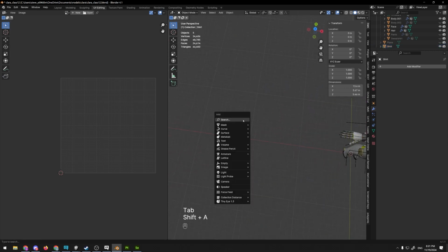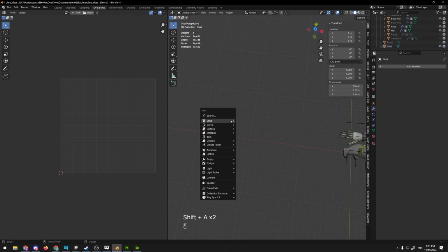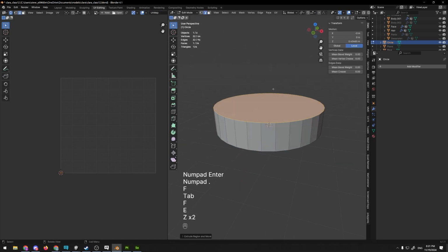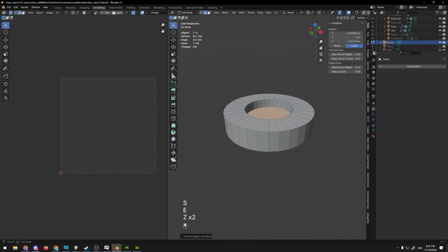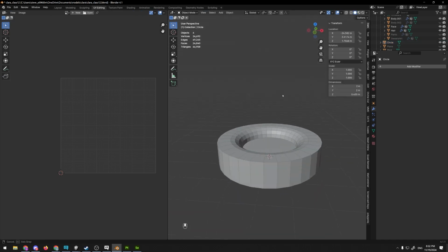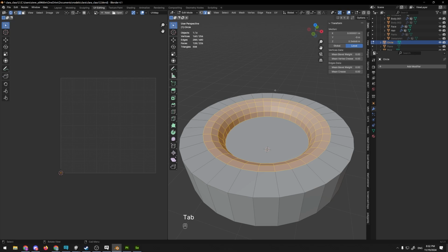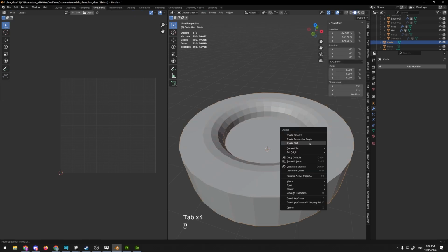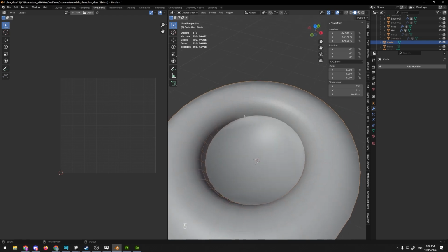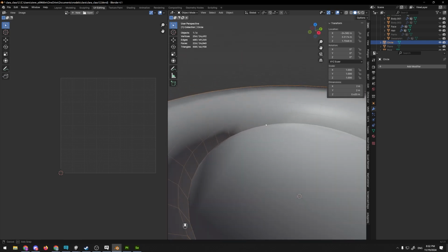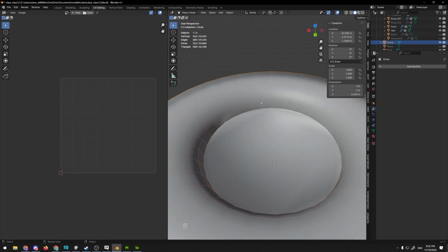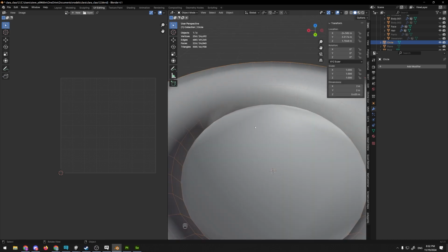If I were to do a simple hard surface modeling tip over here and make a circle, fill in the circle, extrude it up, inlay, extrude down, bevel, like that. So I made this, whatever you want to call this. It's almost like a bowl, but not. This is shade flat right now, so you can see the definition on every single square. If we were to shade smooth, this whole interior section looks really weird. The shading doesn't look consistent across the interior, and that's because it's trying to blend our normals outwards.